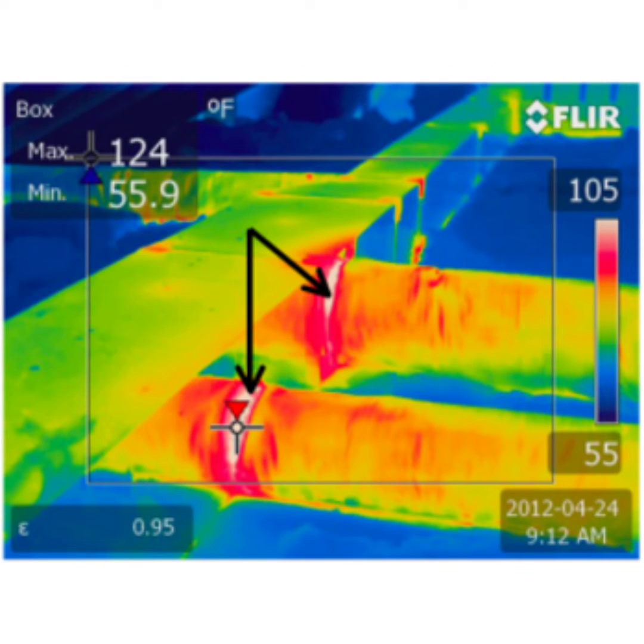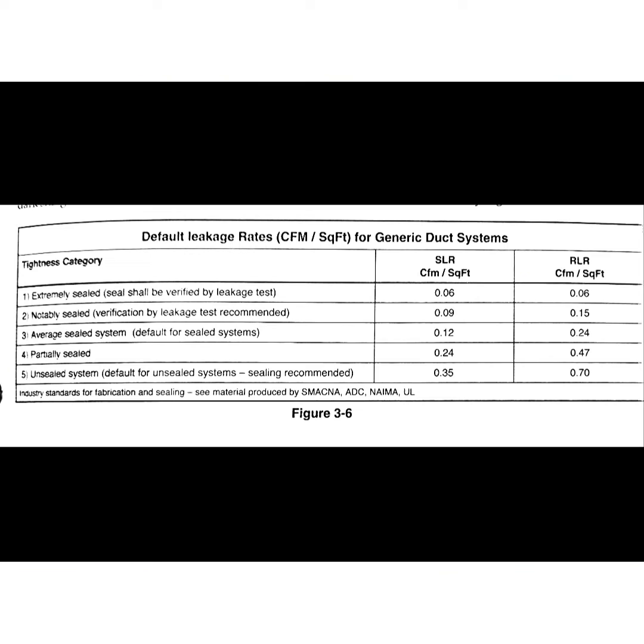The problem with calculating duct leakage is it's very hard to measure accurately because we only want to calculate the duct leakage in the return duct, because that's the path that dry air will enter into the house. The supply air duct leakage isn't really a factor. Well, how much of a factor is that? Well, it's hard to say. It depends on how bad the ducts leak and how often the blower runs.